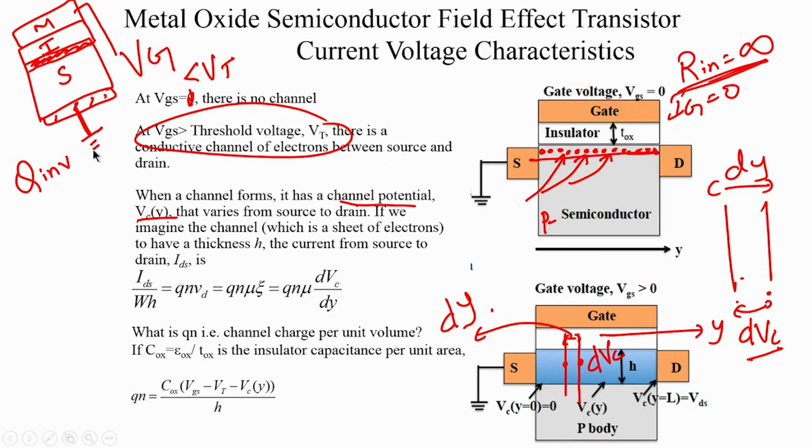and this was with respect to the grounded back contact, and it had generated this inversion layer. If you go back you will recollect that this inversion layer was basically Qn, where n was the number of electrons per unit area, which was nothing but Cox into Vg minus Vt, where Vt was the threshold voltage. That is the way we defined the number of electrons per unit area, because Cox is per unit area.